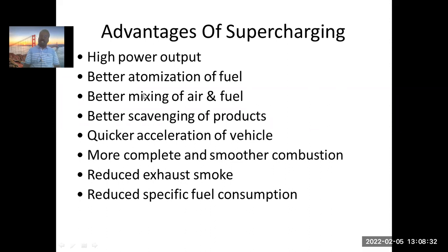High pressure fuel. Yes, exactly. Because we know what we said: how much should the injection pressure be? More than the pressure inside the cylinder. Now the pressure inside the cylinder has increased, so what do we have to do with the fuel? The pressure with which we inject the fuel has to be increased again, which means we are now getting more resistance for the fuel to go in. With more resistance, the probability of breaking the fuel into smaller pieces will be more. Correct? And that means better atomization.